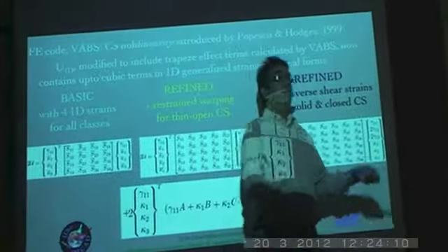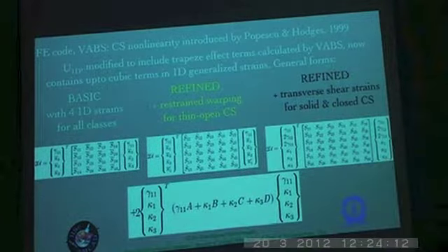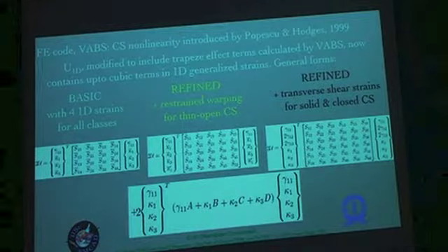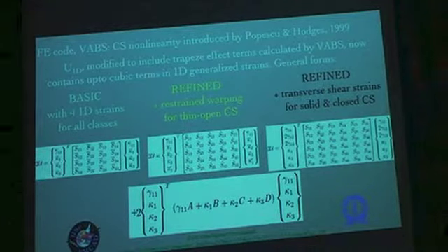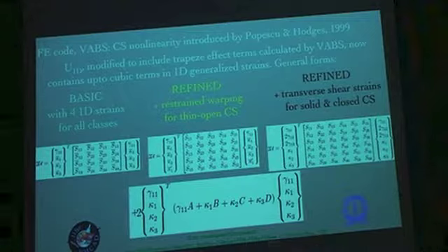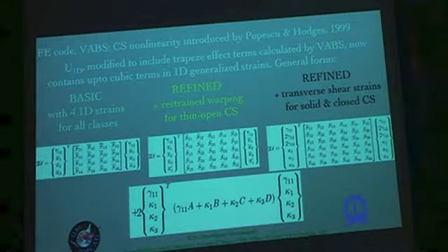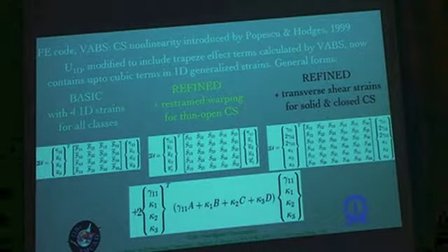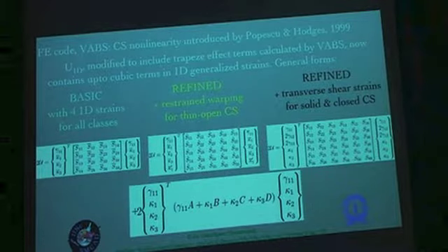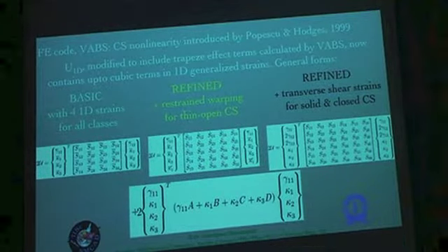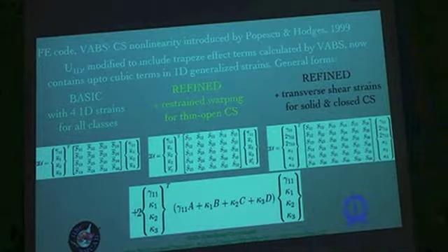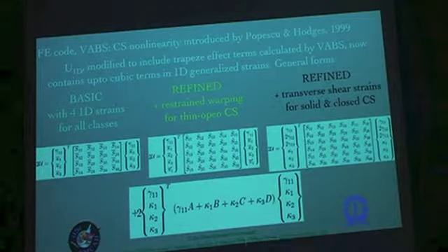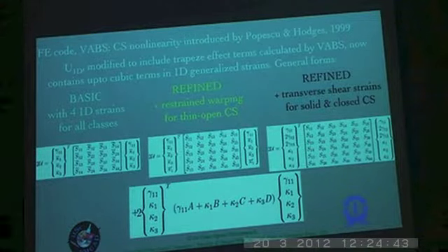So now whether it is a thin plate or shell or a thick plate or shell, the next order approximation, this asymptotically correct zeroth order approximation, comes without having to make the Kirchhoff-Love hypothesis, like the normal remains normal to the mid surface and it doesn't change its geometry, etc. You don't need to make that. Even without making that, we can derive using the variational asymptotic method and show that this is the result which Kirchhoff and Love got by making those assumptions. Just that those assumptions were not necessary in order to derive this.